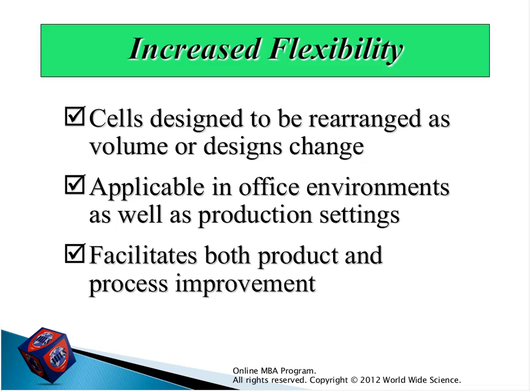If the next step is, for example, assembly line number 3, number 3 should be built beside number 2, and number 2 should be very near to number 1 for easier movement of parts or material in process throughout these departments or units.